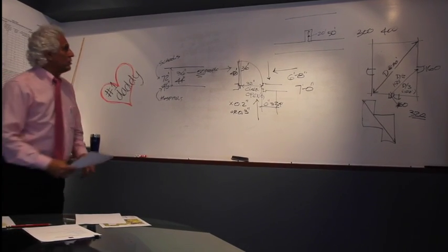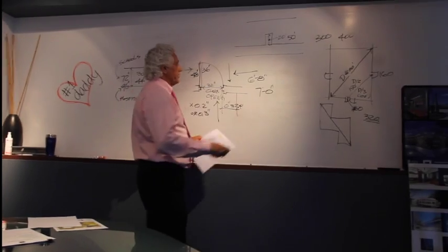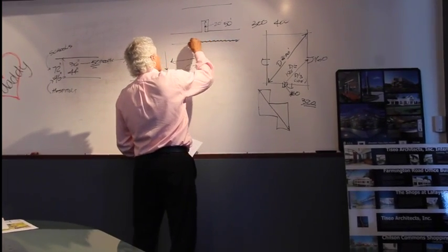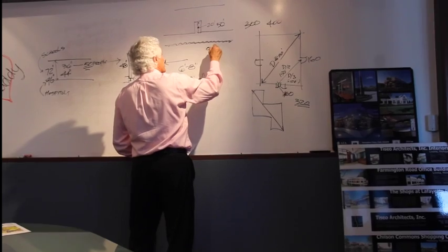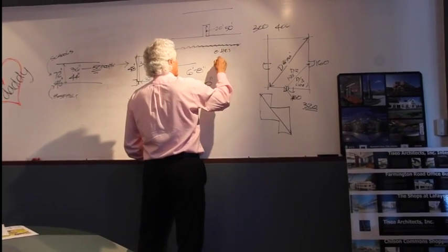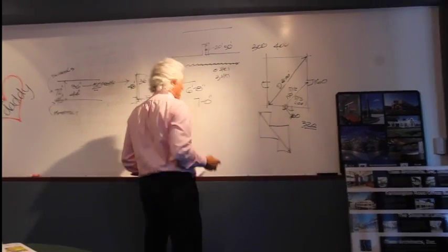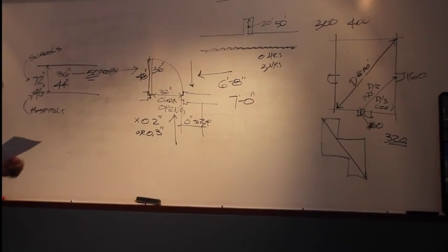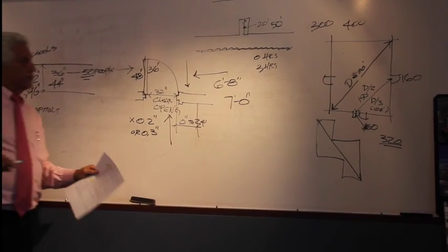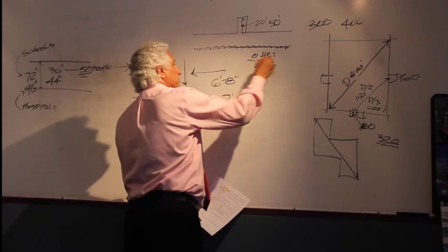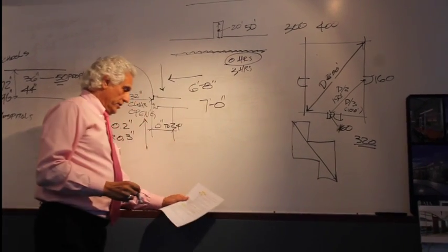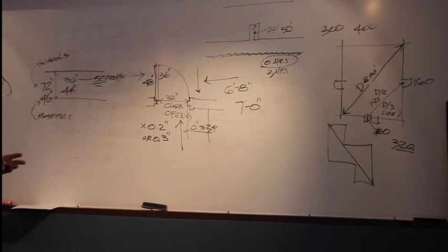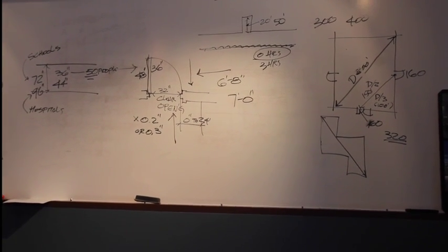Also, the corridors, the means of egress, the stairs, all these exit components may require a rating anywhere from 0 hours up to 3 hours. And it all is dependent on the use. And if you sprinkle the building, then you don't need any of these requirements. Sprinkle the building, you require 0 hours. Again, that's obviously a big add to a building's safety, to have a sprinkler system.